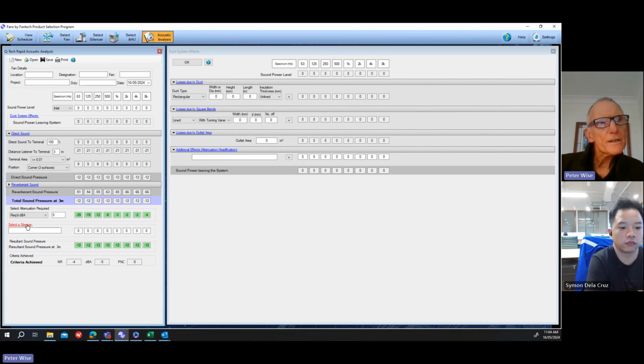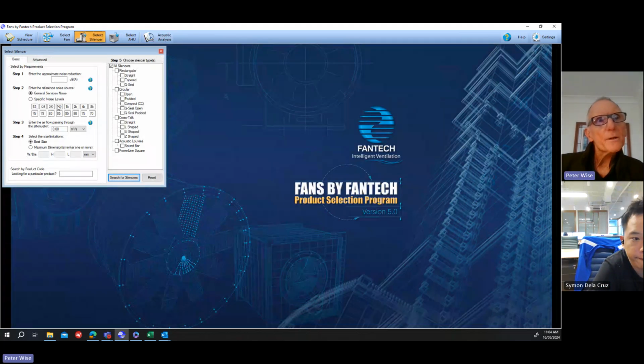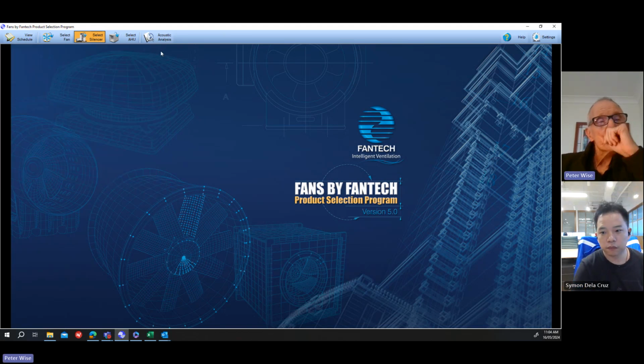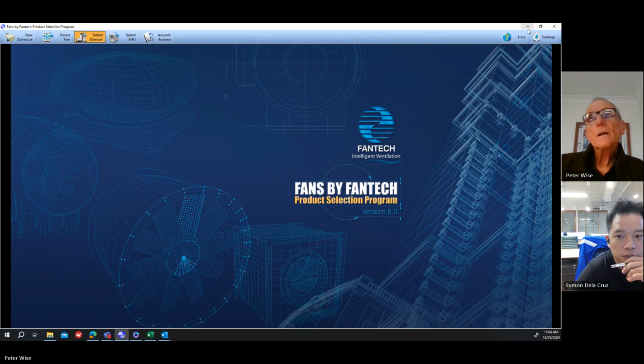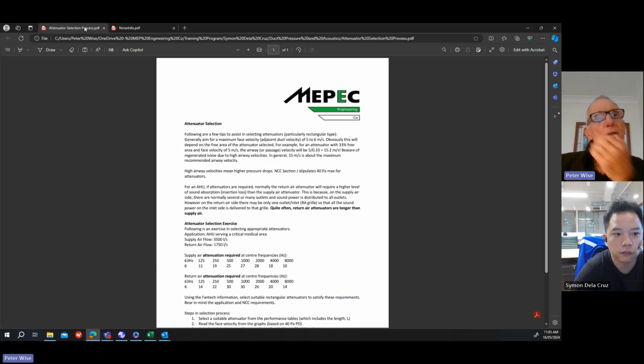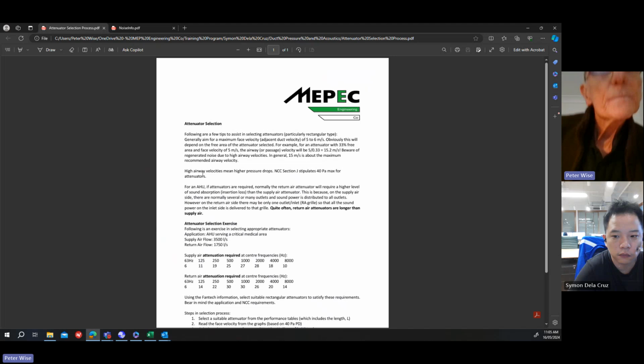So if you click on select a silencer, you can go here and actually select a silencer. But what I want to talk to you today about is a manual way of doing that. If you want to do a quick assessment of an attenuator, so you're not waiting on a selection from a supplier such as Fantech. When they do a selection, they'll give you all the data you need, including the pressure drop and so on. But you can do it yourself.